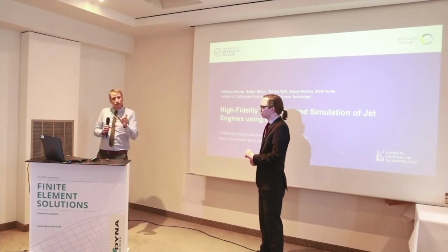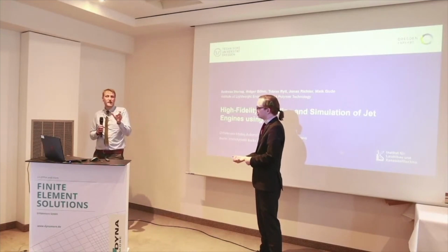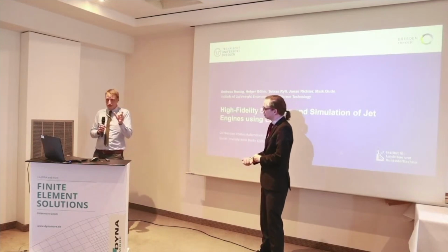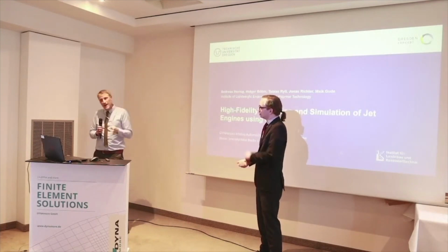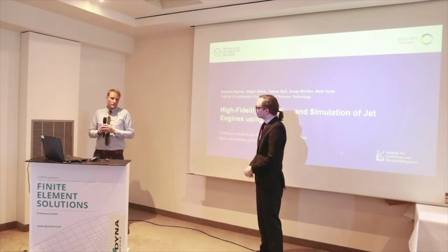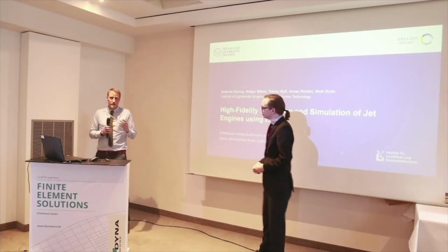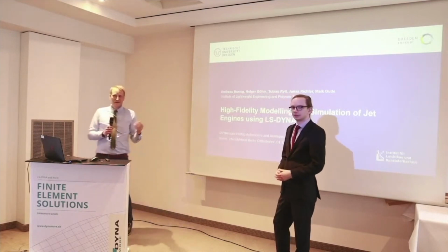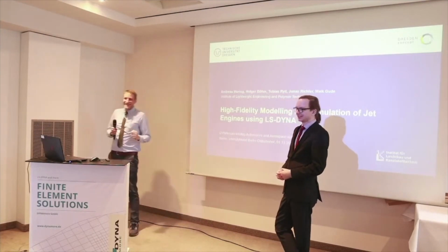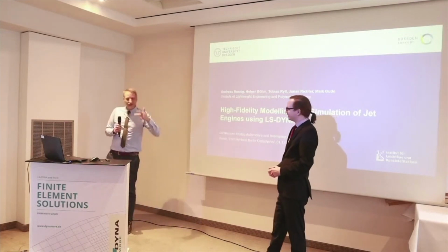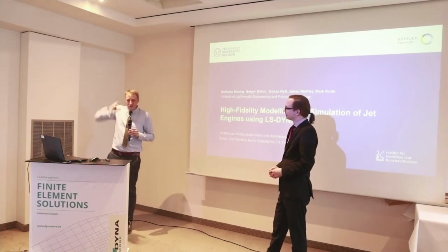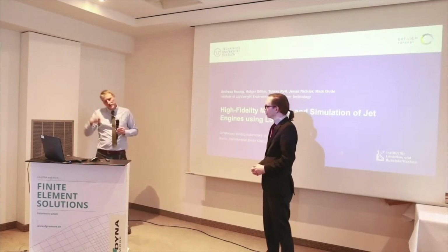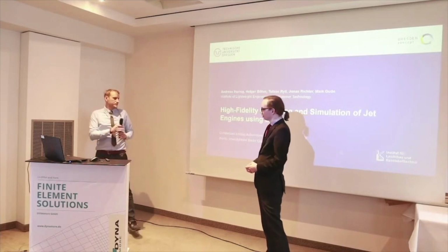With this, we were able to model in thickness direction the intralaminar shear failure and tensile and compression failure. And the interlaminar behavior was done by cohesive, I think it was 33, I think. 138, exactly, 138. So we did it a little bit differently. It's not how you typically do it, where you go for the circumference direction; we went into thickness direction.